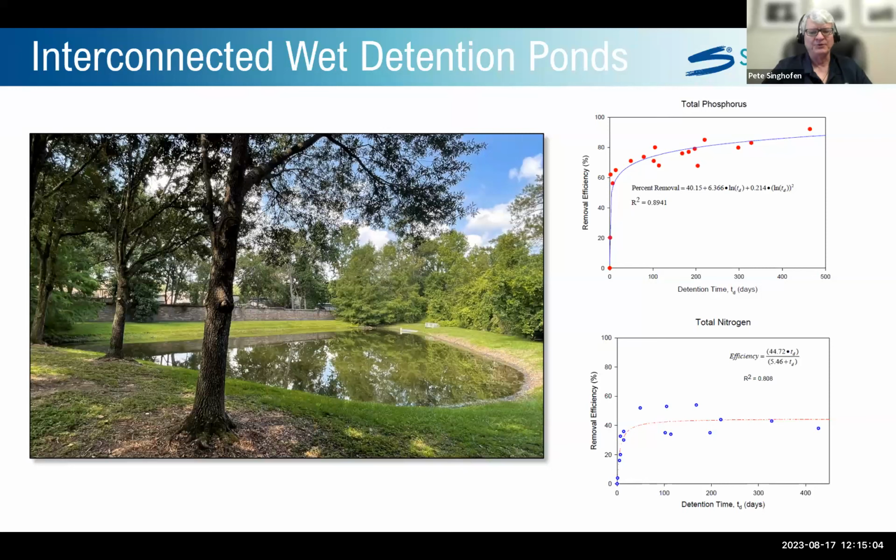By putting a U-wall underneath it, if you don't do that, if you just put it right above the soil, the velocities are really high and they'll suck the sediment from the bottom and clog it up. The ones I've seen that have been most effective, and when I was designing these, we would use the U-walls, and that's almost fail-safe.